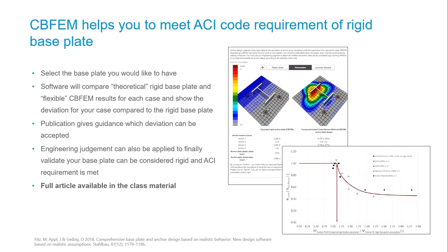If you know more, or if you have a special condition, and you know that all these negative effects on the anchor design from a non-rigid base plate are not kicking in because of this and this, you can for sure go beyond. So the software is open. We don't want to restrict you, but our clear recommendation is to stay in this window; for the tests we have done, we have not seen a negative impact, right? That's the approach we are going to follow. And again, the article and some publications are available.